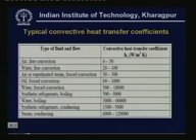Then if you have forced convection, you have higher heat transfer coefficients. In forced convection, if the fluid is air or superheated steam, then the heat transfer coefficient varies from 30 to 300. So you have one order of magnitude higher than free convection. This is because of the vigorous mixing of the fluid when you have forced convection. When you have oil in forced convection, again you have 60 to 1800. This is higher than air because you are dealing with a liquid. And if you have water, you get a much higher heat transfer coefficient because water typically has a higher thermal conductivity compared to oils. And if you have phase changes such as boiling or condensation, you get really high heat transfer coefficients.